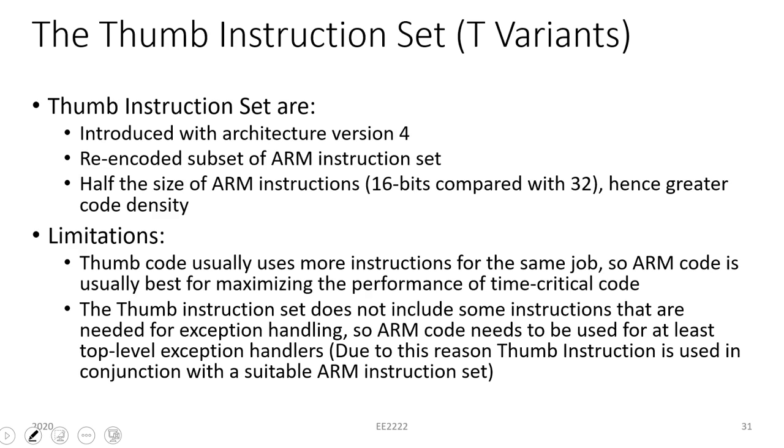Then one of the other factors that we may see particular to the ARM architecture is what is known as the Thumb instruction set that came about with instruction set version 4. So here we have some instructions that are half size, so some are 16-bit whereas others are 32. With these half-size instructions we can have higher density of code, so again a low code footprint, which can be an advantage when we are particularly considering embedded applications and things like that.